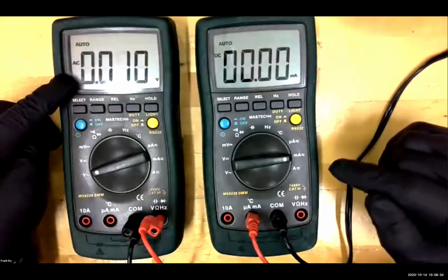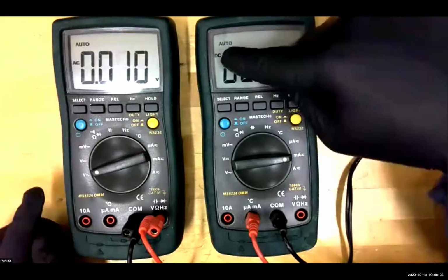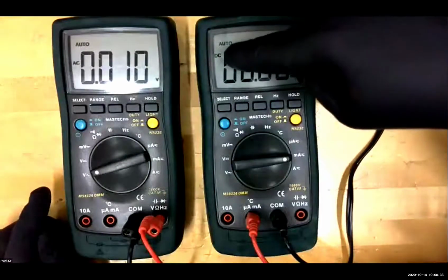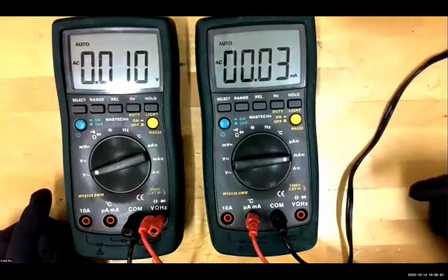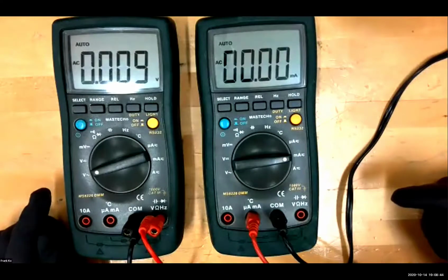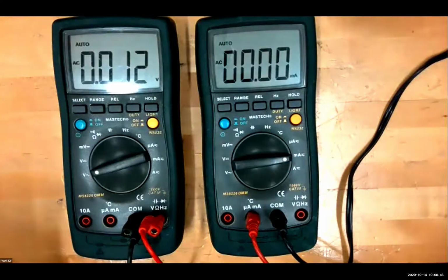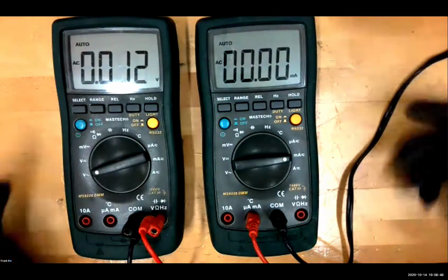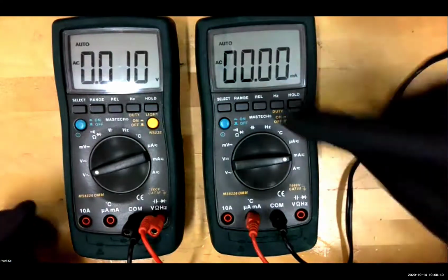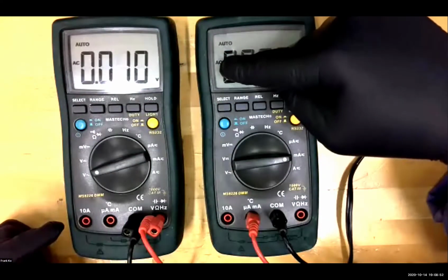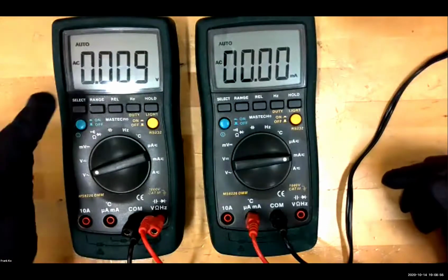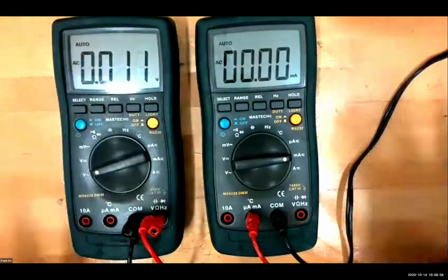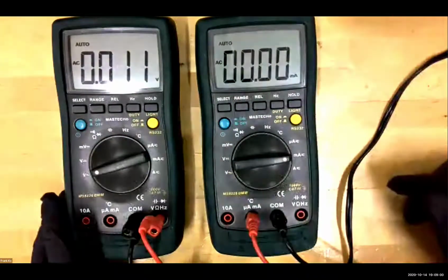Is this set up to measure AC? Nope. What do I need to do? Hit the select button right there. And that's how you, if you say these meters are not measuring what they're supposed to measure, I come over, and if I see DC there, you're going to get a little rap on the head, right? Because I'm reminding you right now, AC, AC. If you leave it on DC, you'll get erroneous results.